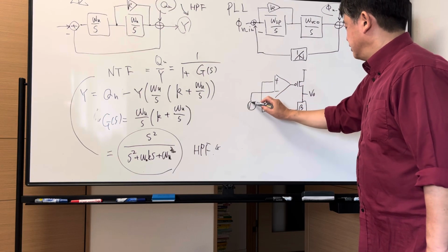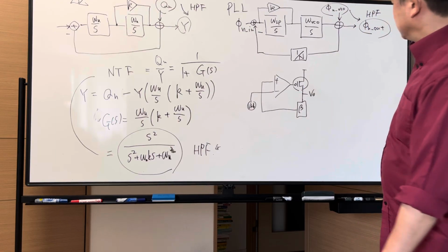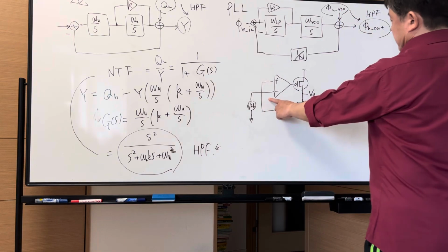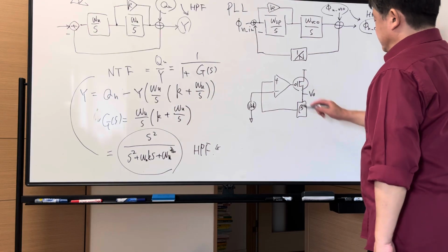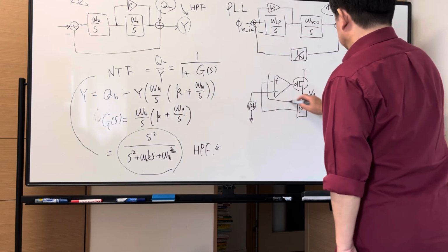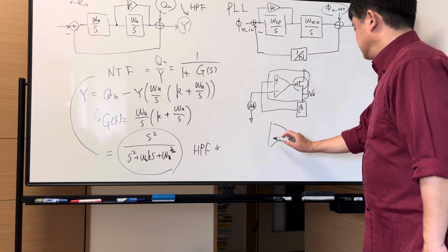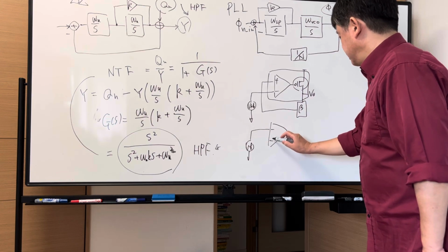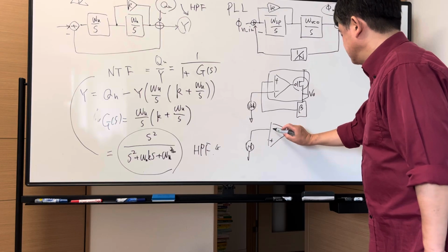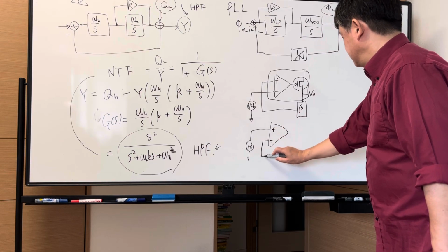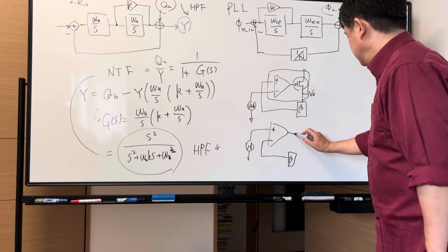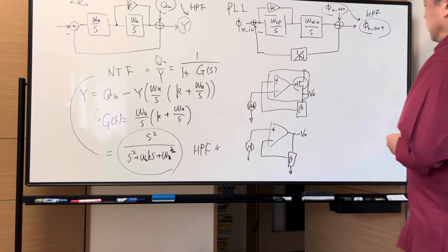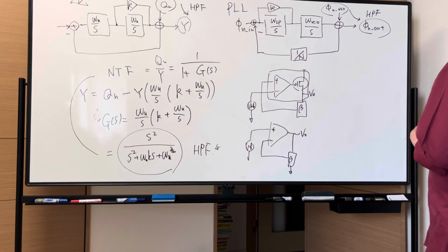Because of the polarity of this P-channel MOSFET, the voltage difference is applied to the negative input of the error amp here, but simplified, VREF is applied to the plus input and the feedback signal is applied to the negative input. This is a series shunt feedback topology.